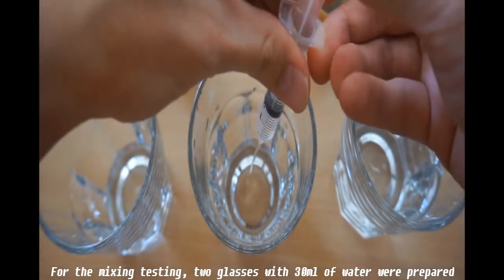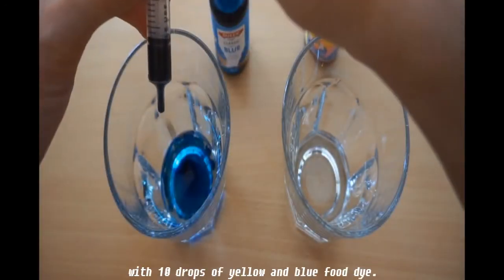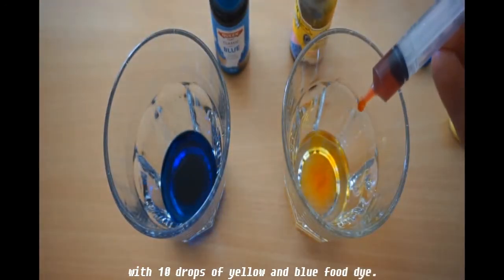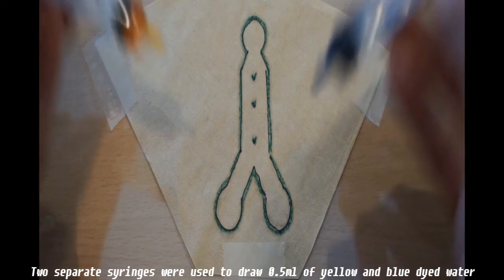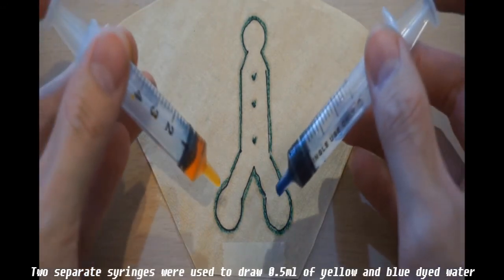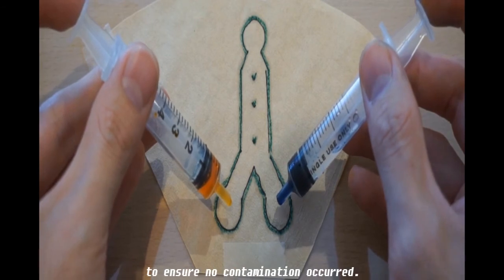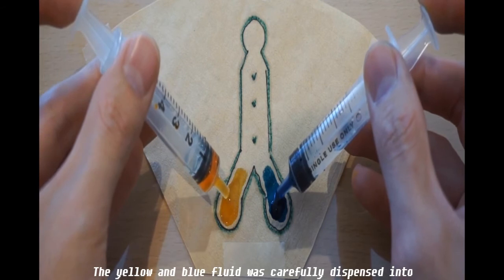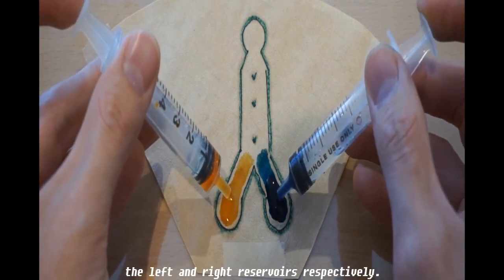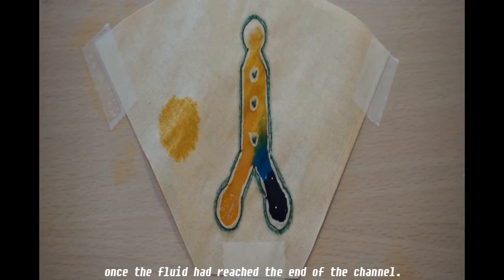For the mixing testing, 2 glasses with 30 milliliters of water were prepared with 10 drops of yellow and blue food dye. The samples were then taped onto a clean, dry and non-porous surface. 2 separate syringes were used to draw 0.5 mL of yellow and blue dyed water to ensure that no contamination occurred. The yellow and blue fluid was carefully dispensed into the left and right reservoirs respectively. A photo of the sample was taken once the fluid had stopped flowing.